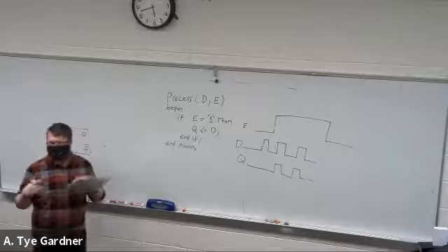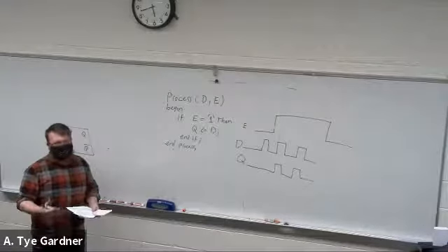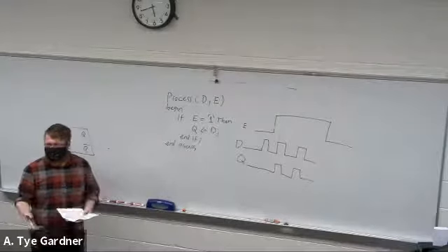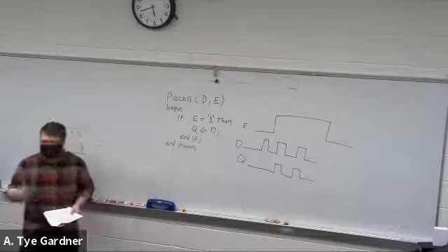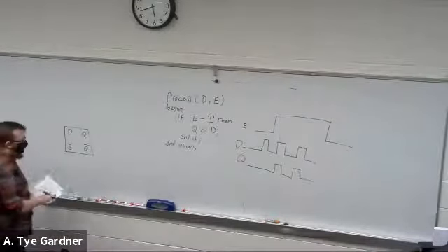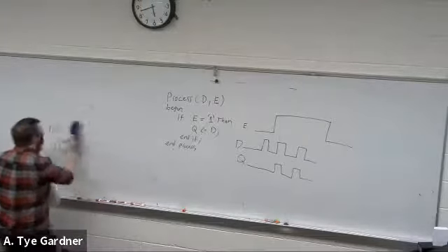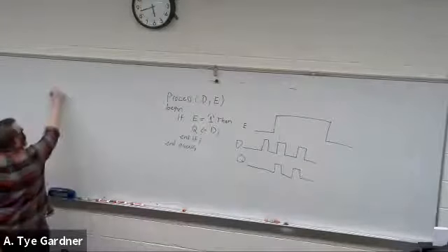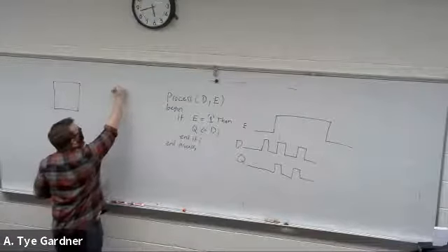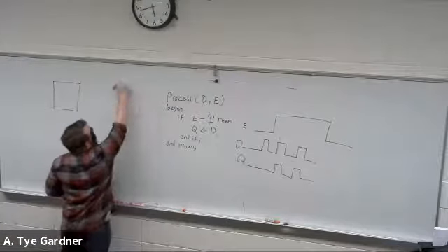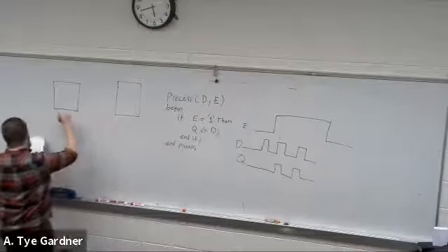We want to know at a given time. Or another way of saying that is we like to clock our signals. We like to say at the moment a clock hits, that's the value we care about. And we can build a clocked system using just 2 D flip-flops.